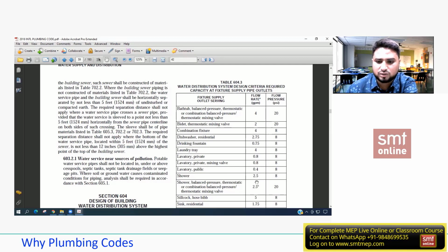So this shower demands about 10 liters, or 2.5 gallons per minute. If it gets that, the shower is served properly, and this requires 8 psi. This is constant worldwide. It's not that Western, Eastern, or Asian countries have it decreasing or increasing. It's standard.